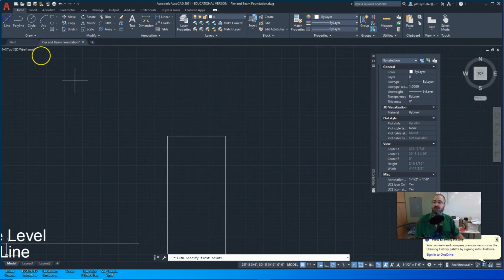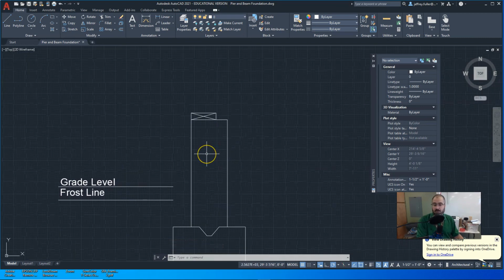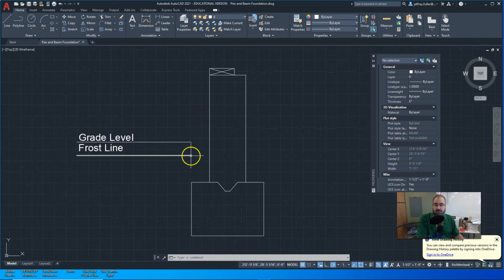So we're going to come over here and just keep it even with this outer wall. We're going to go up 1.5 inches, then come over 5.5 inches, and then come straight back down. And then we're going to put an X. X marks the spot. What that does mark is that it's a cut piece of lumber. Okay. So there is our piece of lumber. That is our mud seal sitting on top of the foundation wall, and our flooring system will sit on top of that. So we're done with that part. Okay. Get all this done and then continue on with the next video, and we will do more stuff.